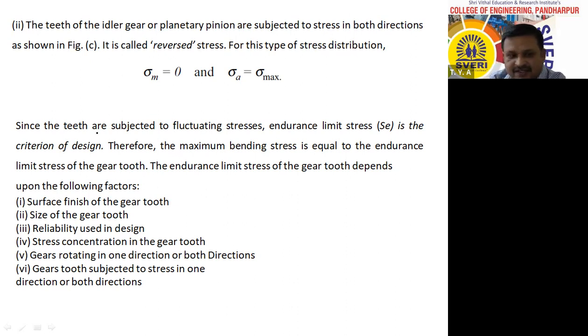Remember that. Therefore, since the teeth are subjected to fluctuating stresses, endurance limit stress SE is the criterion of design. Therefore, the maximum bending stress is equal to the endurance limit stress of the gear tooth.